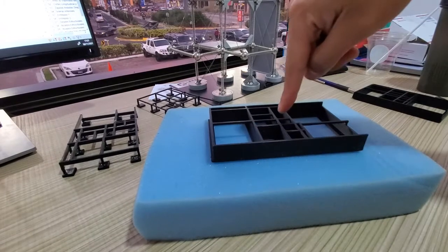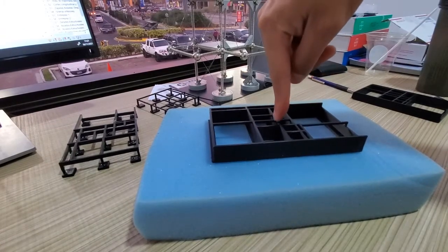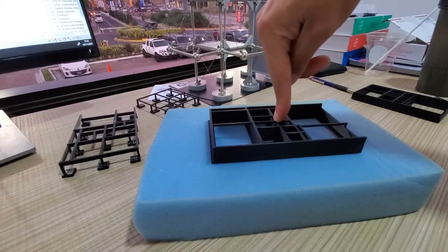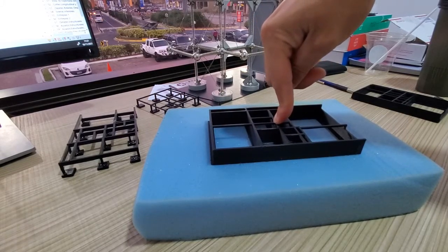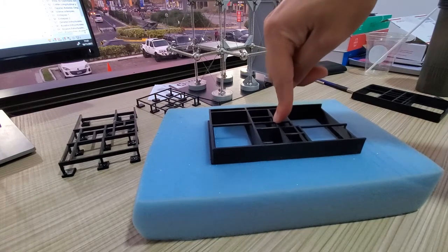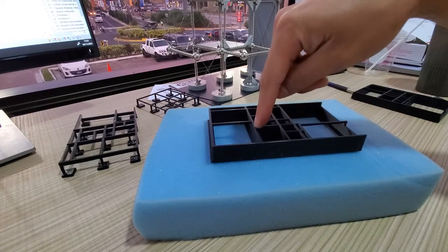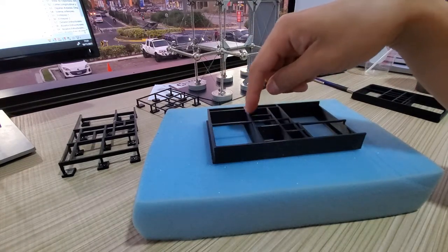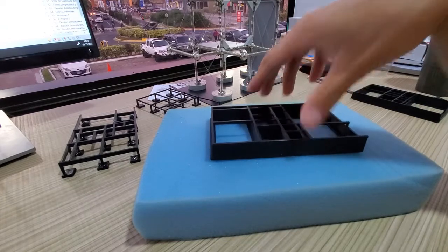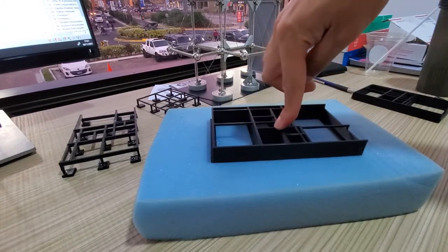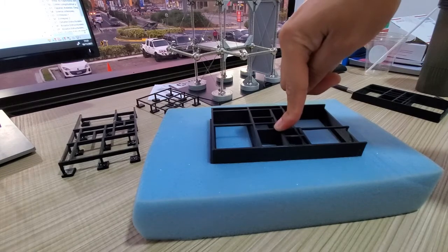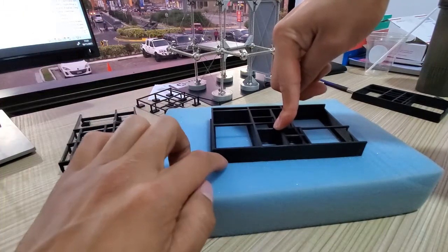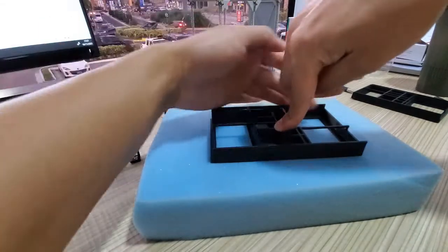And you can see in this model, when I apply a higher load, for example, concentrated in a central region, the stiffness of the whole system is transferred to almost all the neighboring continuous footing, and the settlement of the house is expected to be nearly the same in all the area.